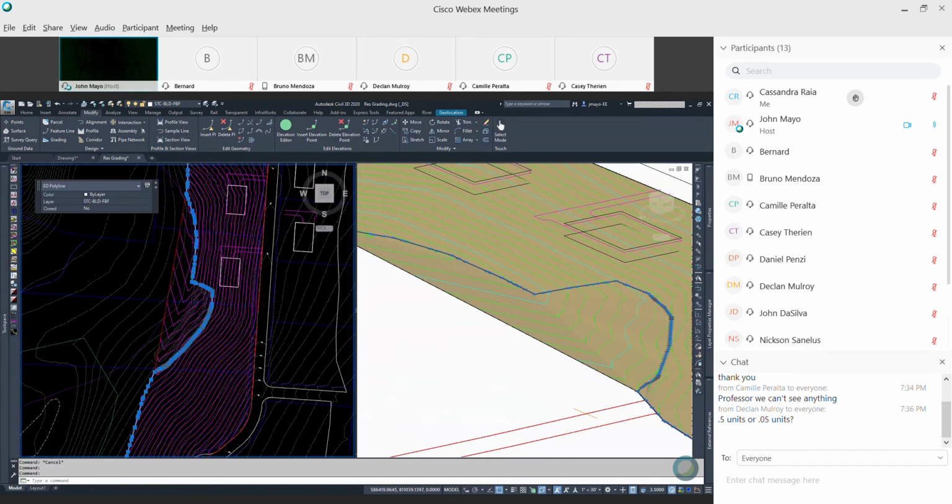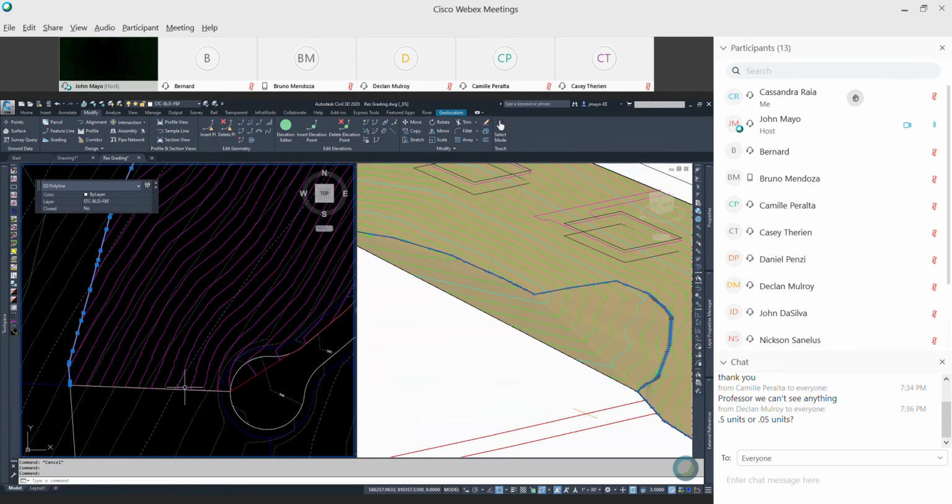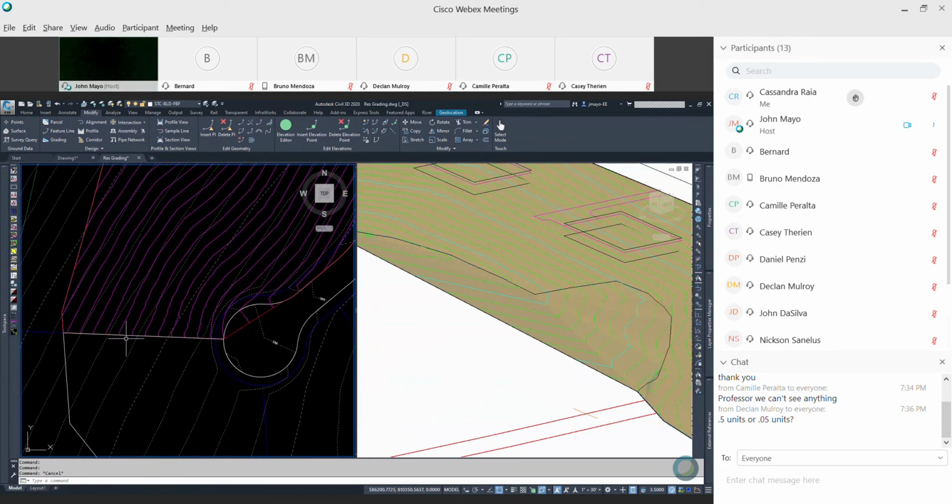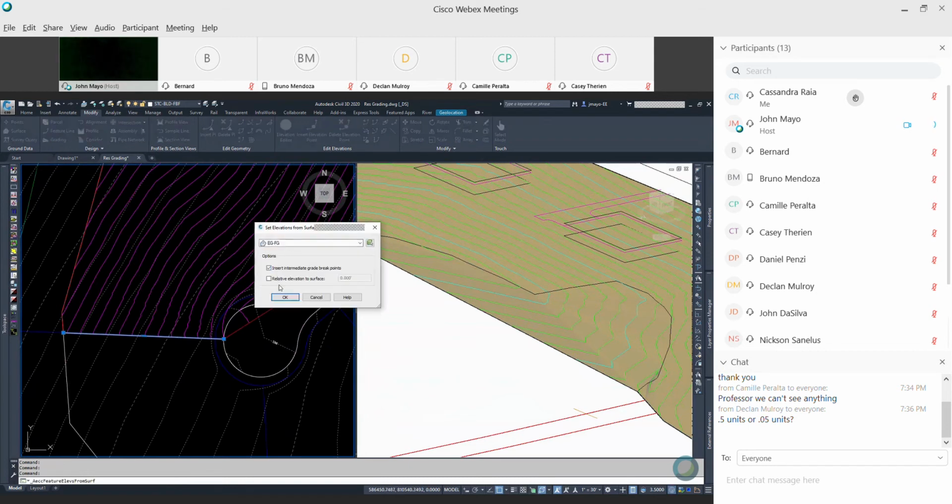And I will do that later either with the border or by deleting triangles. And the border I could make with that 3D polyline, right? This is a polyline. If I want those contours to match with the existing, I assign the elevations from the existing surface.